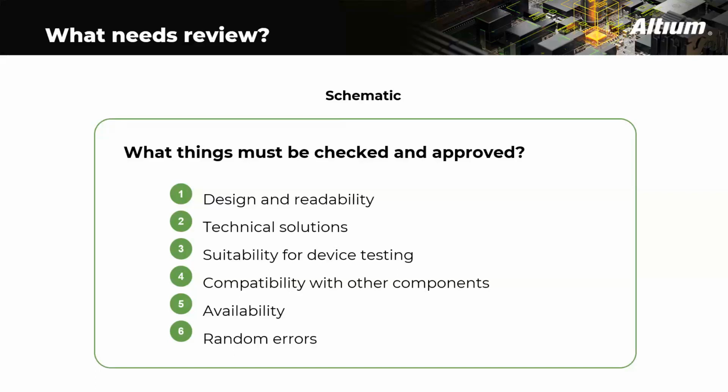There is suitability for device testing. In addition to how well our devices operate, we need to check to see if we have the necessary jumpers for firmware, debugging and testing included. Do all control circuits have test points? Fourthly, we need to check compatibility of our components and modules with other components. Do the pinouts of connectors, interface, supply voltage, and so on match?